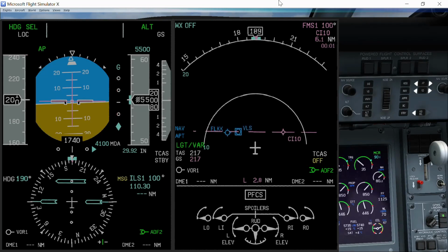I'm going to pause the simulator. Look at what has happened. Can you see the glide slope indicator? You can see that you are very high because the glide slope indicator is very low. If the glide slope indicator is very low, it means you are very high. So here's what happens when you are closer into the runway or intercepting the glide slope after the final approach fix: you come in high. If you review the diagram which I sketched on the presentation, you will appreciate a three-dimensional scenario of this sort of situation. Okay, so this was about it basically. I didn't want to show anything else on this one.